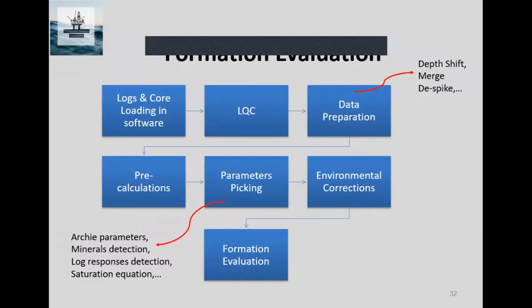At the end, you will see the modeling and petrophysical evaluation using the software. In parameter picking, Archie parameters, mineral detection, log response detection, saturation equation, RW detection work. And data preparation maybe needs depth shifting, merging, de-spiking, and other functions.